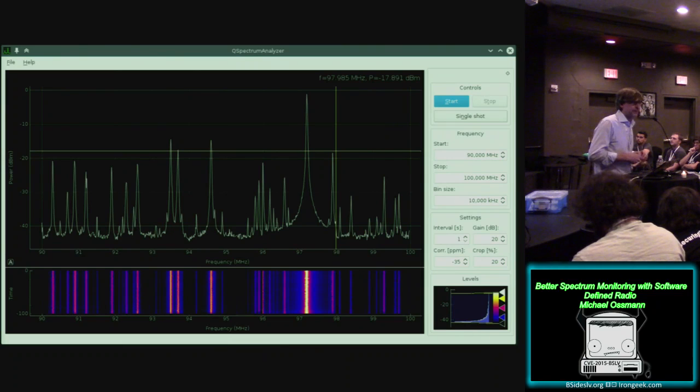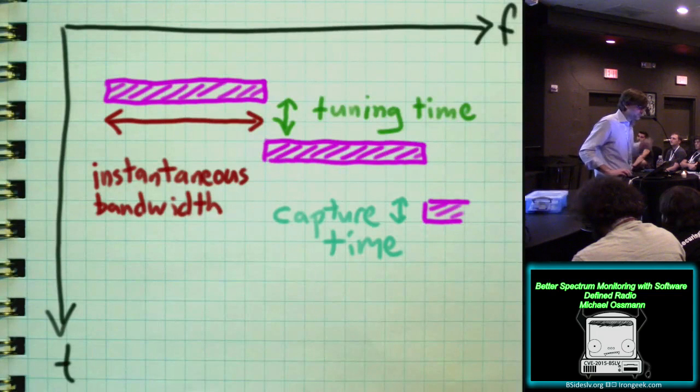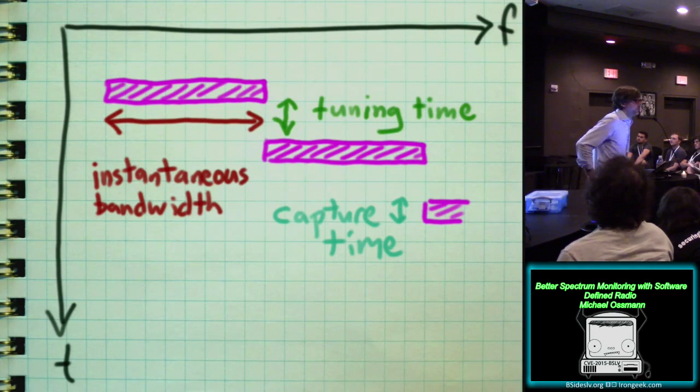You can think of SDR platforms, and I often do, as low-cost RF test equipment. Effectively, that's what it is. We have a low-cost, uncalibrated signal analyzer and signal generator right here. And we should be able to do a lot of the same things that people have historically used very high-cost tools to do. So, looking a little bit closer at the digital sweeping.